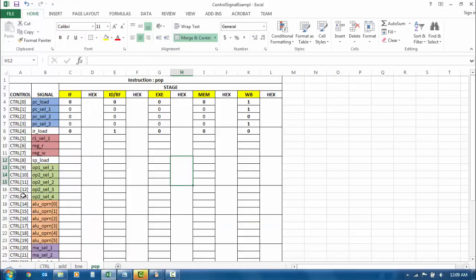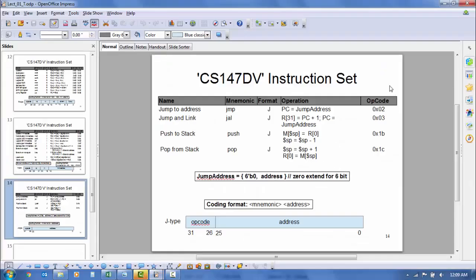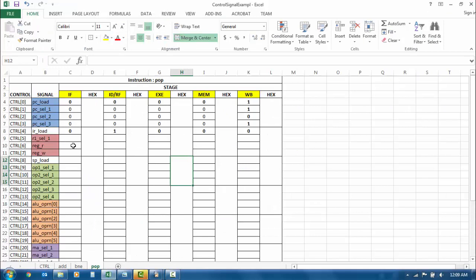So for us, do we have a register read at this point? No, the stack pointer is a separate register, so we don't have anything to register read, right? So we can just put it on hold for the register file. We're not reading, so this R1 selection is not very important here, but we're writing back. So that must be 0 1, right?